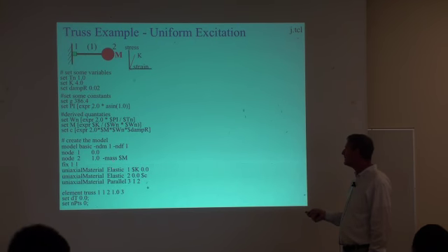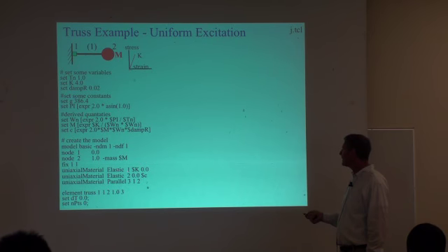I'm going to create my model. I'm going to add node 2, and add a mass, $m, which is based again on what the period should be for the structure. I'm going to create my elastic material. I'm going to create another material which has the damping in it. The elastic material, this C is for the damping matrix. I'm going to put those two materials in parallel and give it to my truss.